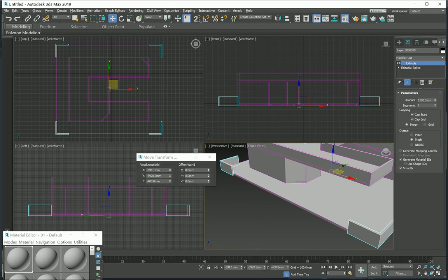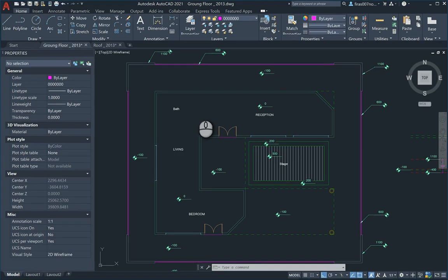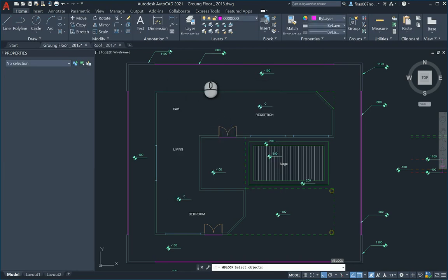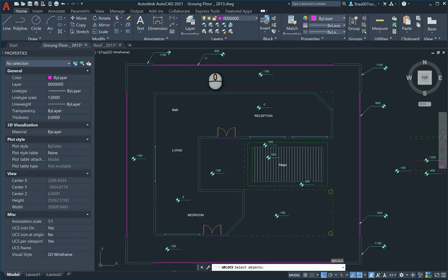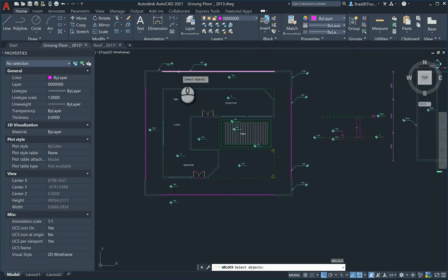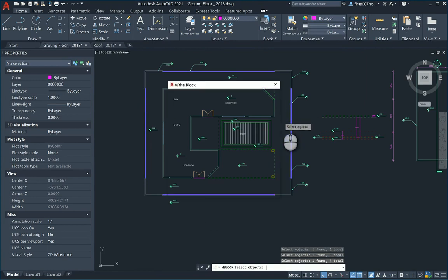Back to AutoCAD, and I can do the same thing. Right block, select object. Those end up at 600, and starting up at minus 400. So it should be 1400 and then 600. That should be the extrude value of 1000, or you can just draw them in the section. Now you know the way. I'm not going to repeat it.